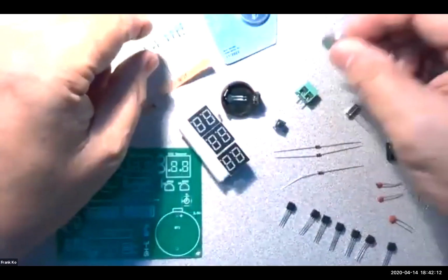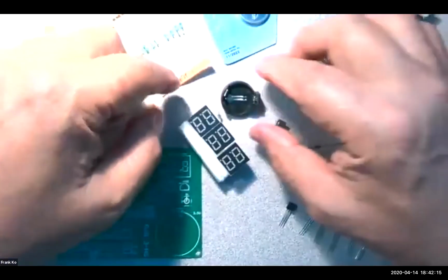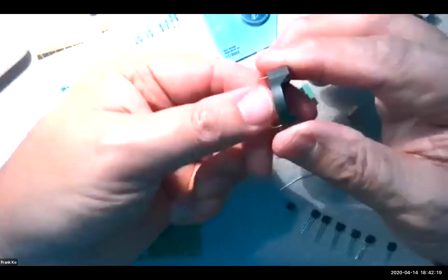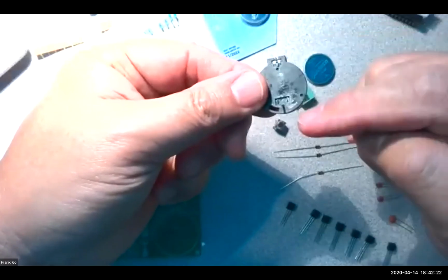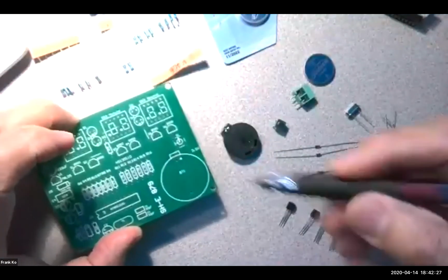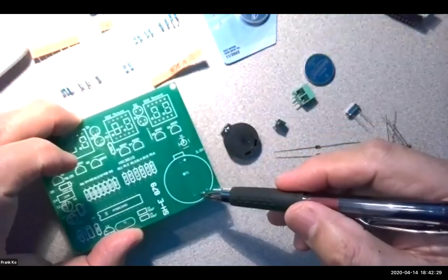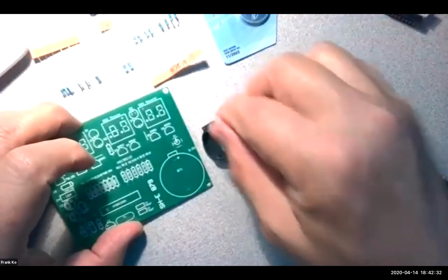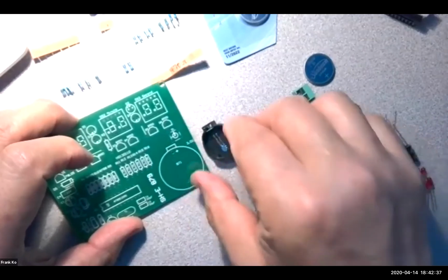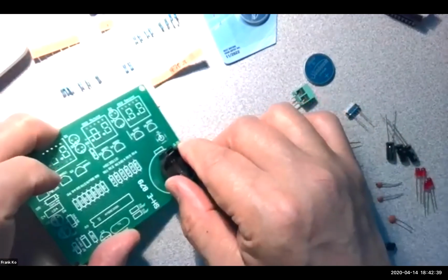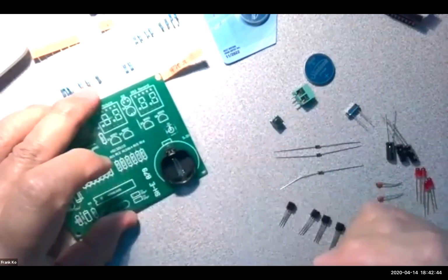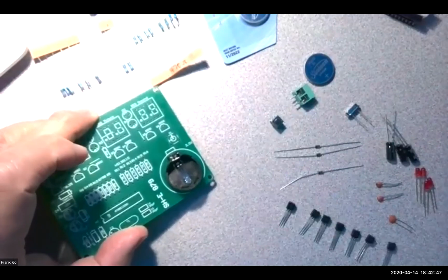So very reasonable for these batteries. I have a coin battery here, and it will go into a holder. The holder has a positive terminal and a negative terminal, and that's marked on your board as positive and negative. How do you know to set it up? Well, there's a diagram here that shows a little white notch. That white notch is for this part of the battery holder, and it goes in with the black notch matching the notch up here. So that's the correct orientation for the battery holder.